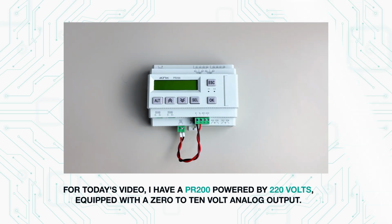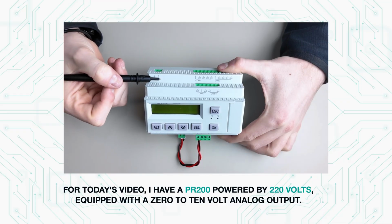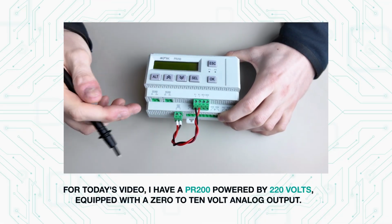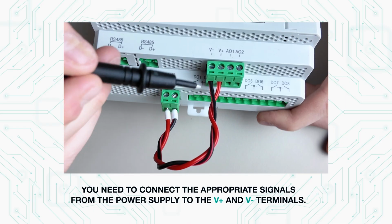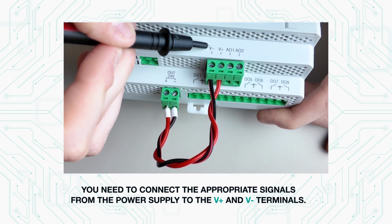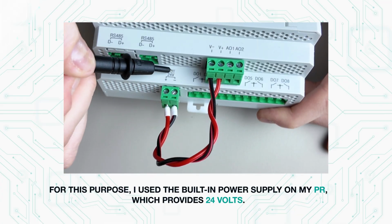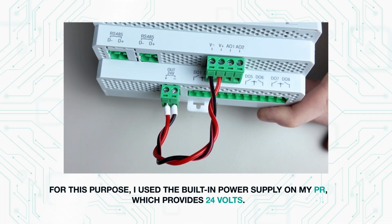For today's video, I have a PR200 powered by 220 volts, equipped with a 0 to 10 volt analog output. According to the connection diagram for this analog output, which I reference from the PR user manual, you need to connect the appropriate signals from the power supply to the V+ and V- terminals. For this purpose, I used the built-in power supply on my PR, which provides 24 volts.